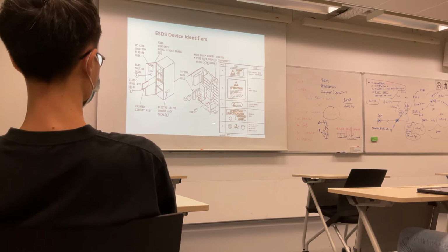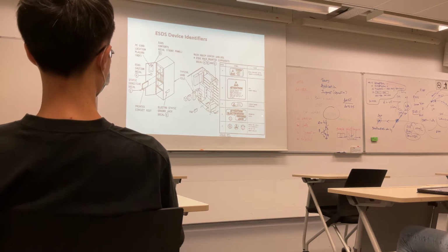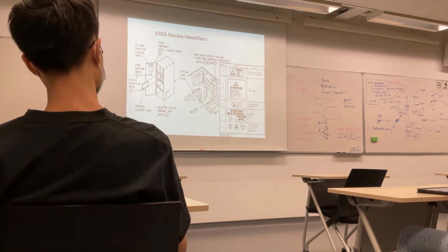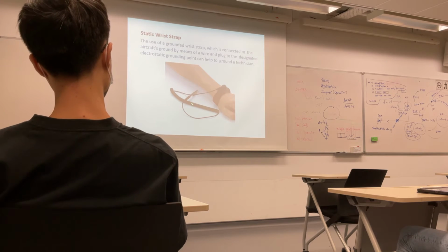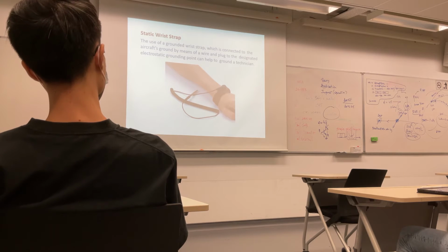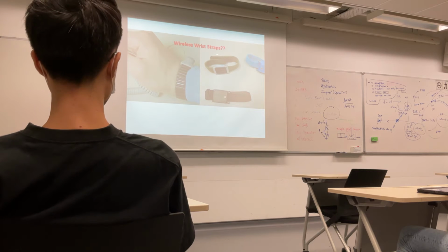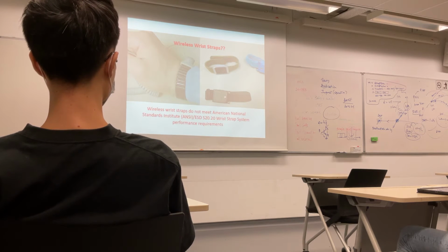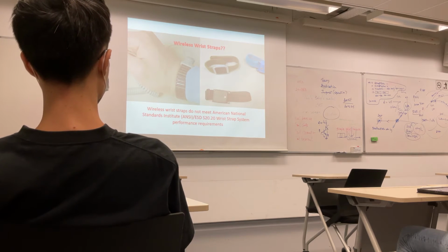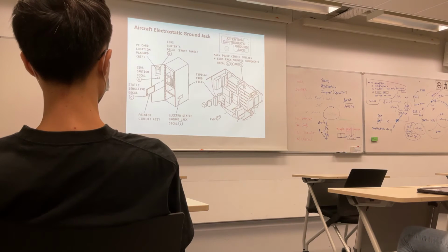If you go to an aircraft, you'll see these caution decals, a standard aircraft decal. Your wrist strap is to ground, it's not to prevent generation. And somebody was trying to sell a wireless wrist strap. Actually, that's fake news, there's no such thing. It doesn't meet a standard. And then how you test it.